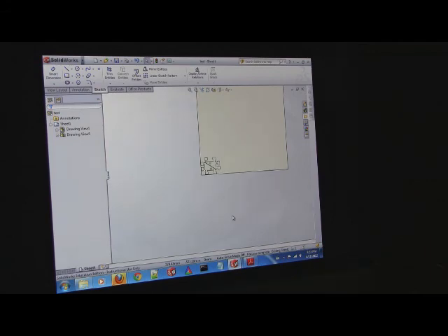Say this is a circle I'm going to laser cut. It's going to drill somewhere, and it's going to draw a circle. And say this is my bearing hole, 21.6 millimeters. What size is my bearing outer diameter? 22. Okay? So why would I make this 21.6 millimeters?